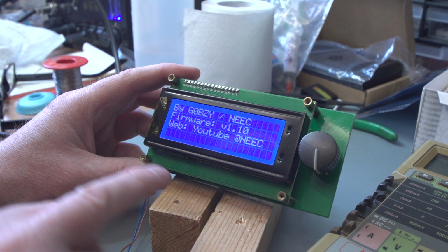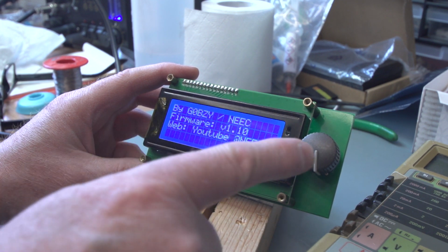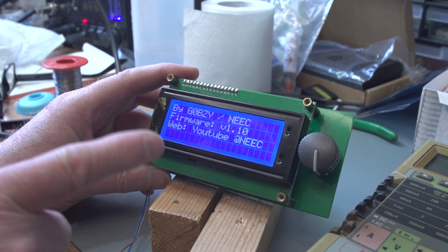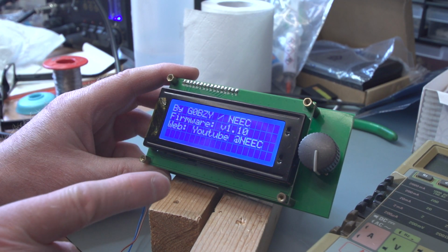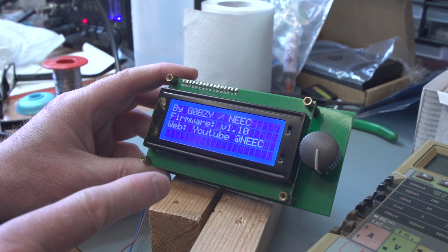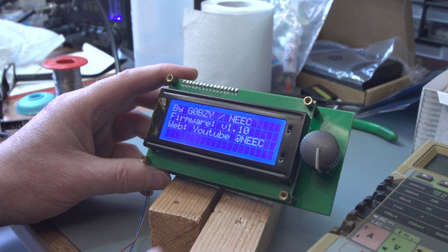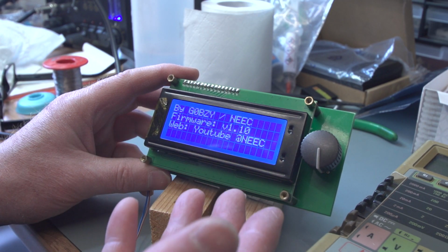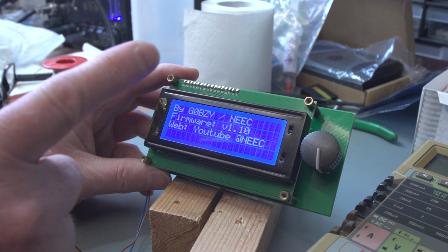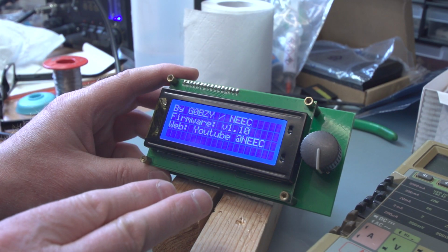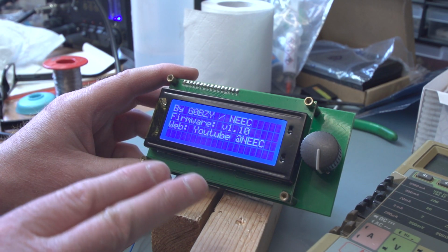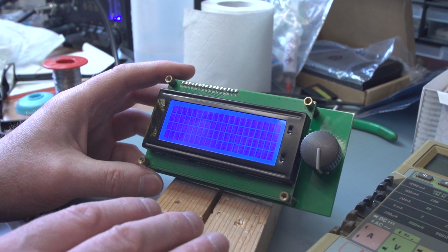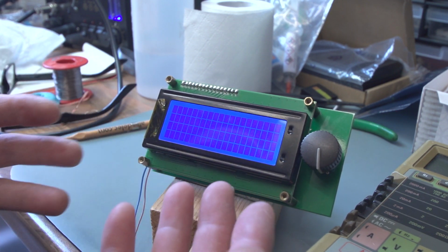Now, it seems to be taking a long time to reset, and I think I know why. It's because I haven't actually programmed the fuses yet for the clock speed, and it's probably running on the internal clock and divided or whatever. If I'm not mistaken, this should come out of a reset eventually, but we need to program the fuses within the MCU to tell it we want an external 16 megahertz clock. I think that's what's going on. There we go. So everything's very slow.